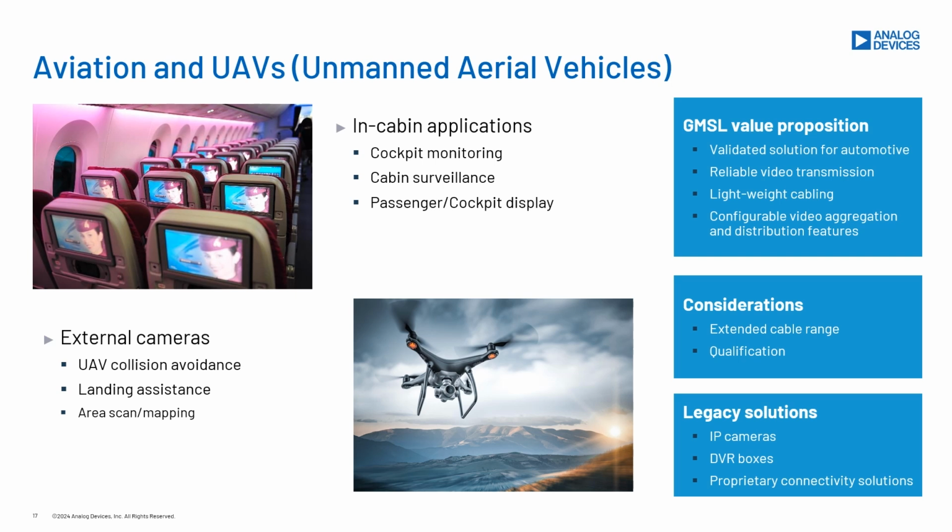Sometimes these applications require extended cable length and have more stringent qualification process that are less open to the general public. There are some off-the-shelf GMSL repeaters and lower loss cables to help extend the reach of the GMSL links, and we are also trying to better understand system-level qualification requirements and regulations to help with a broader customer base.